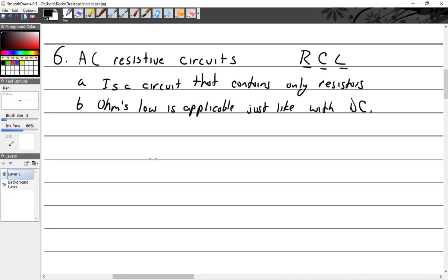You guys remember Ohm's law, right? Yes. And resistors in series, you add them up. And if it's in parallel, the total resistance is smaller than the individual resistors. Oh, our lights are coming back on. All right. And if you're going to measure current, you would measure it in series.